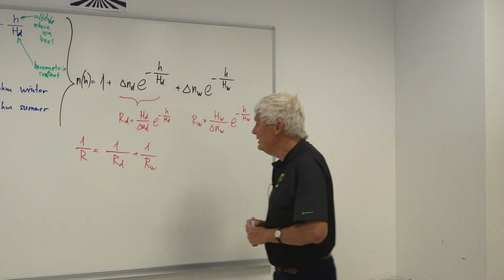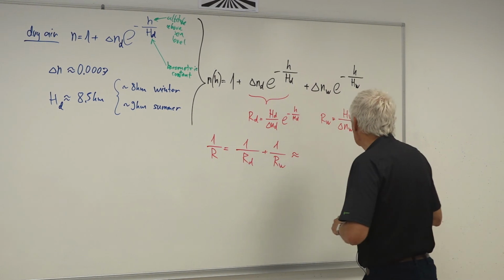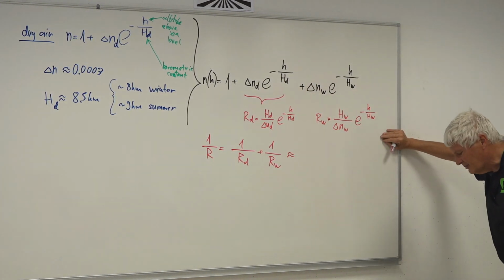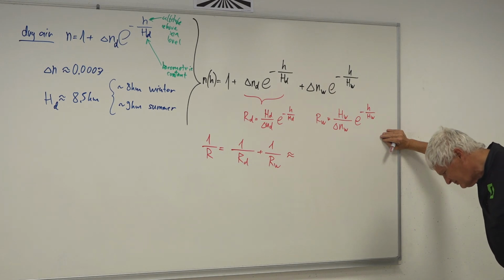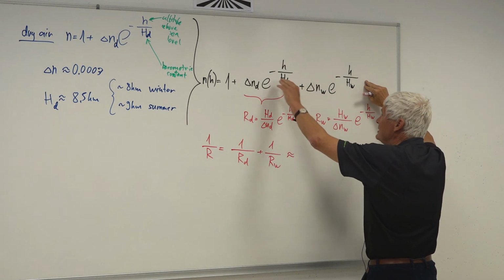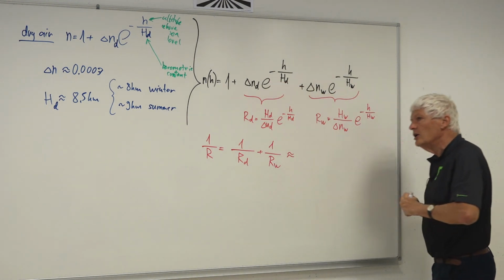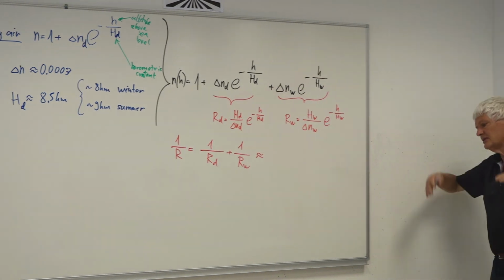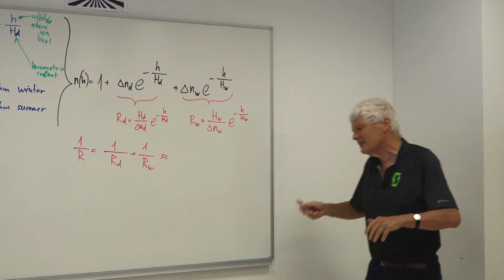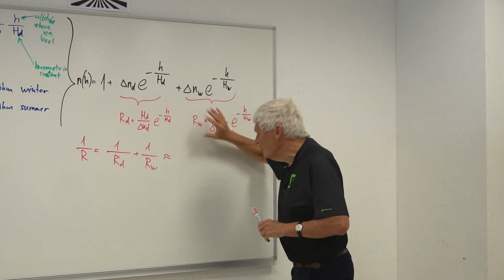And what now becomes r? Now, don't take this word for very accurate. The wet part is usually 10% of the dry part, in normal weather at normal latitudes with some reasonable temperatures in spring or in fall. Not in summer, not in winter, not at the equator, not at the South Pole. Okay, this is the order of magnitude.